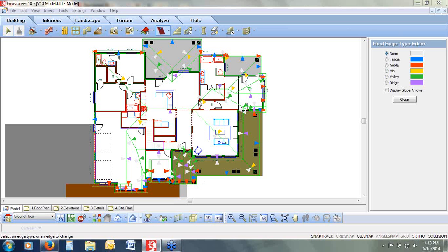And that's what you'll see on the opposite side of every selection. So here I have a ridge, and on the other side there's nothing. But you could change that gray one, if you wanted to, into a double ridge. So if you want to have double material at that ridge, then you could make both of them a ridge line.